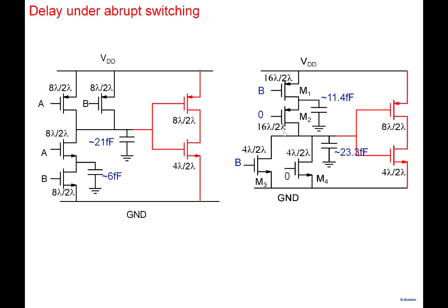The reason why we are doing it is that both of them are universal gates, and circuits you can implement with NAND as well as with NOR. The issue is which one you would prefer. Sometimes maybe you require NOR, so you have to use it, but in case you have a choice, which one would you like to use? So what we are doing is comparing the two. So these are the capacitances. Note that the NAND gate and the NOR gate have the same pull-up strength and pull-down strength, right? We designed them with that in mind here.